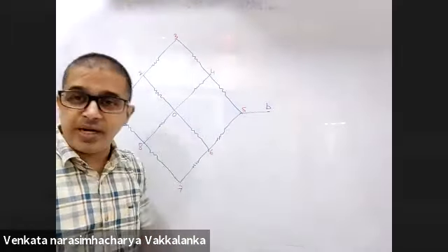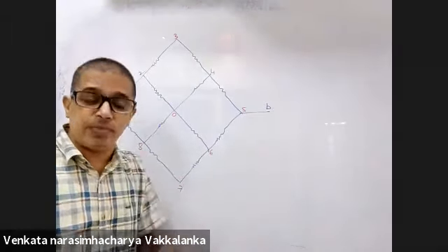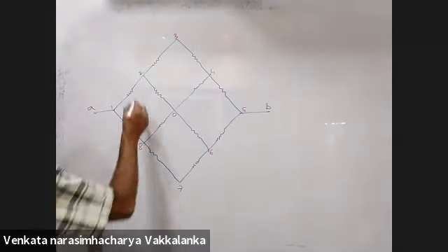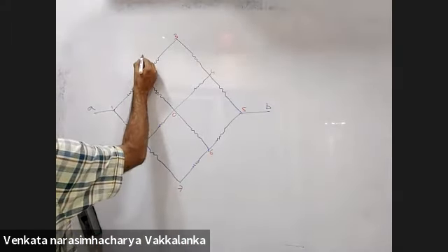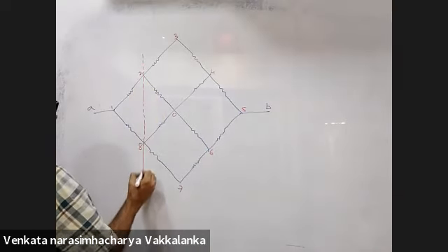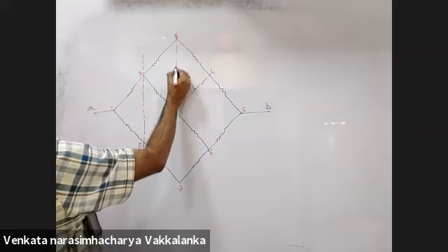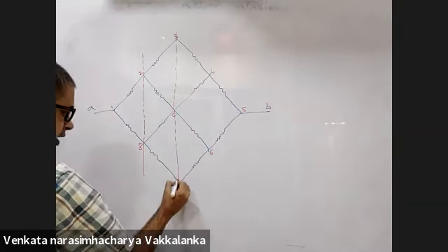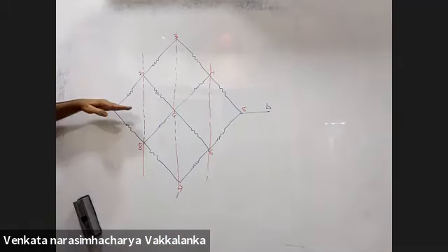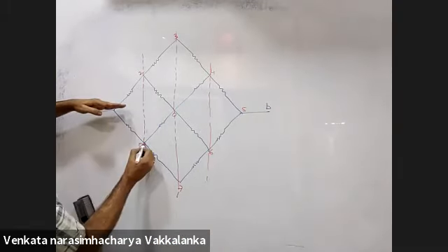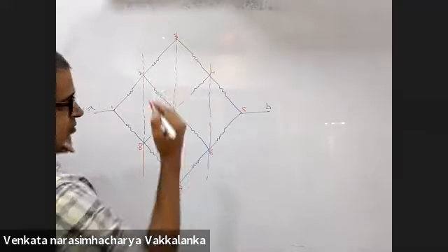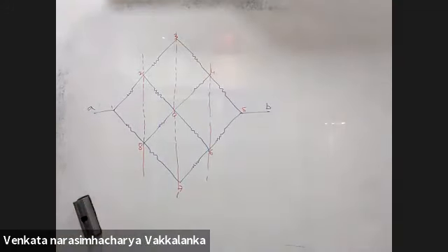First rule of symmetry. Recognize the equipotential points. What do you mean by recognize the equipotential points? You told me all points which come on the perpendicular line of symmetry are equipotential. Perpendicular to what? Direction of current. Current is coming this way. So 2 and 8 will be equipotential. 3, 0, 7 are equipotential. 4 and 6 are equipotential.